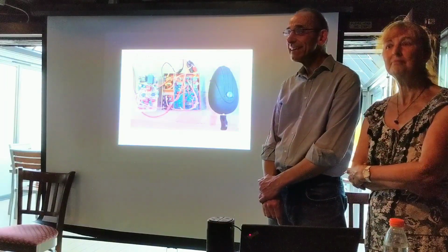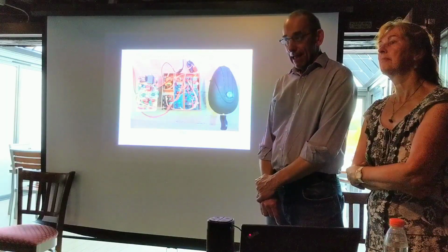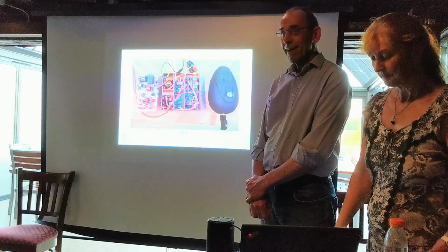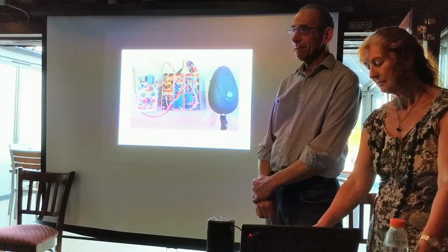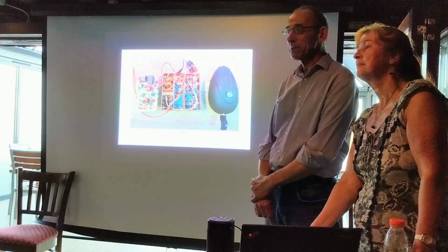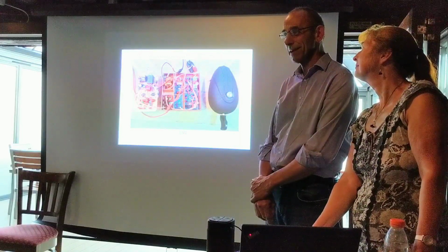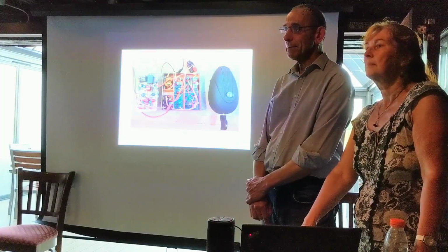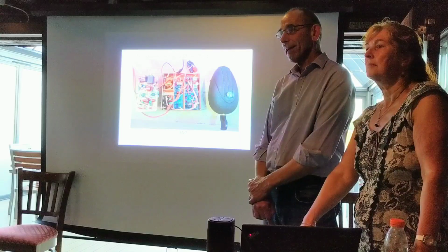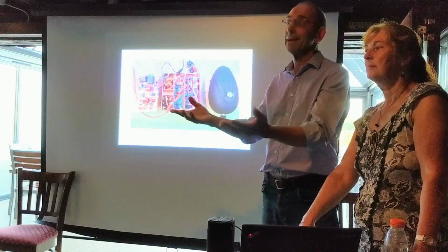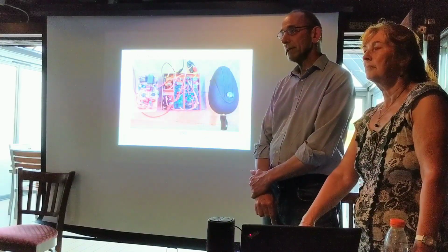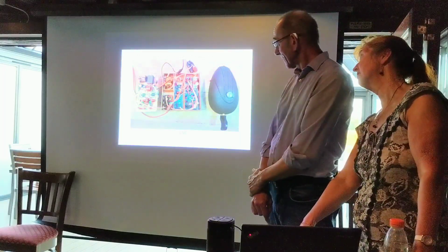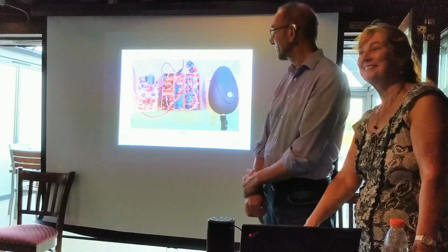Any other questions? What aerial were you using to hear the SAQ? Because it was so clear. I tried and I could just hear it in the noise. Yours was fantastic. Year 1 of that project was, I think I can hear something in amongst that horrific noise. I was actually using a G7FEK, which is an 80-metre antenna, with both the sections connected together, with a large loading coil put on it. But I do have a very good earth mat in the garden. Well, you did have. Did. I did have, sorry, I did have a very good earth mat in the garden.